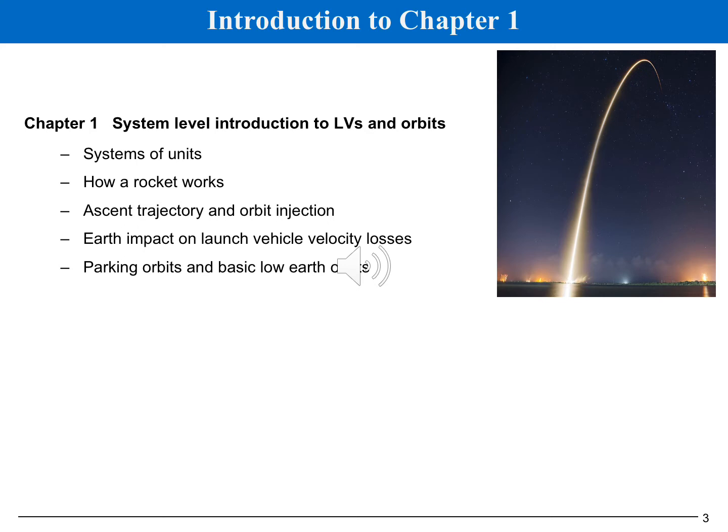Then there's a deeper dive into the Earth-related forces that impact rocket velocity, some negatively, for example, gravity, drag, and engine back pressure caused by the Earth's atmosphere, and some positive, that is, launch location, which is usually helpful and advantageous if you launch from the East Coast, but maybe less helpful and sometimes even negative for West Coast launches. Finally, there's a preliminary introduction to the treatment of orbits from U.S. launch locations until there's a more detailed treatment of orbits in Chapter 5.